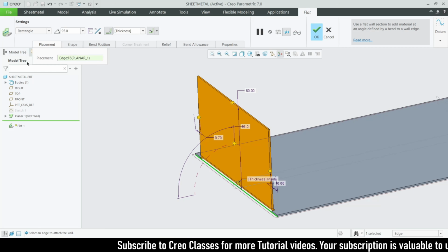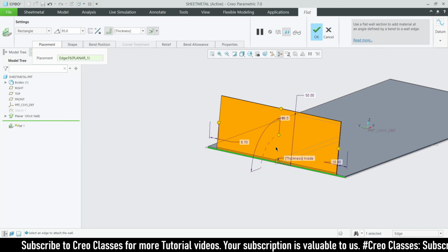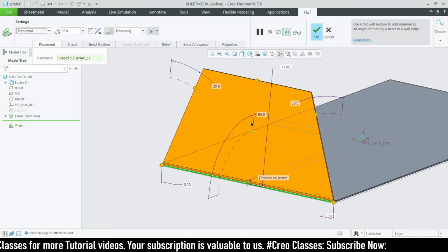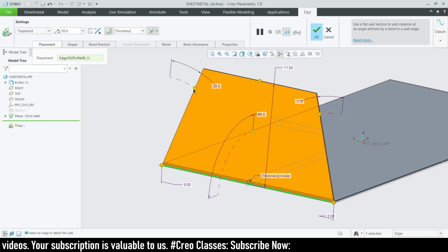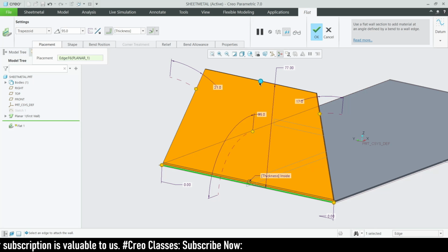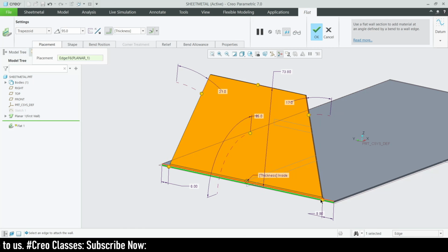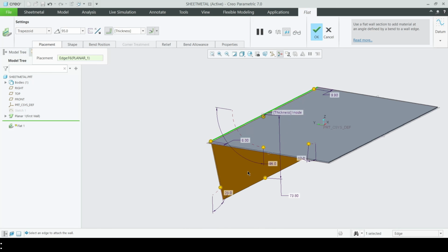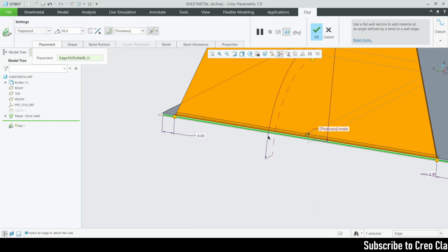First of all, you can see a rectangle here. This is a rectangle shape, right? The next shape is trapezoid. On this trapezoid, you can see there are various options for this side angle, and you can adjust this angle, including the height, and the distance from the edge, the same on the other side, and the same for the angle. Everything will be the same on the trapezoid. I just clicked on the other surface, no problem. Let's click this surface, it will be the same.